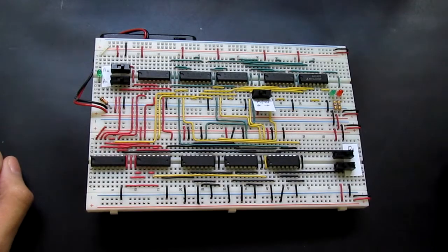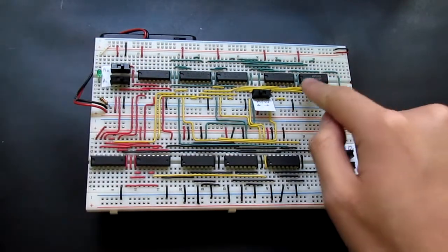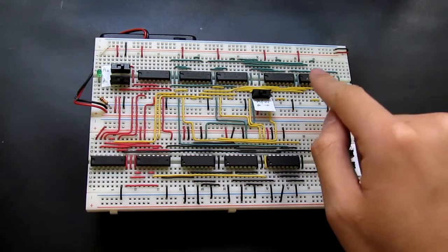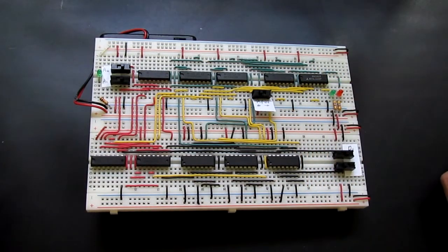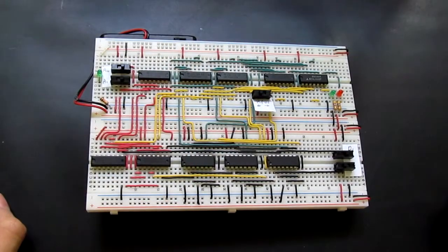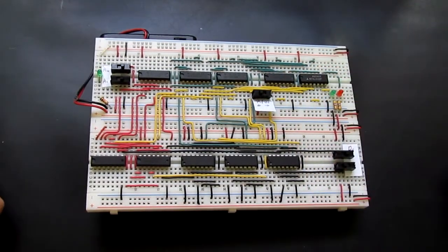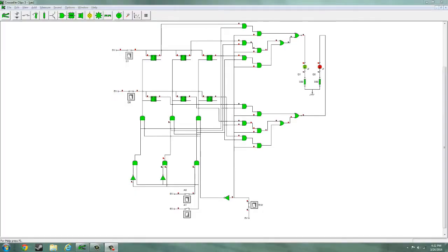It uses one 7404 inverter IC chip, one 7432 OR gate IC, 3 7474 commercial D flip-flop chips, and 5 7408 AND gate ICs. It also uses 5 single-pole double-throw switches to operate the circuit based on the following schematic. In reality, it's fairly simple.